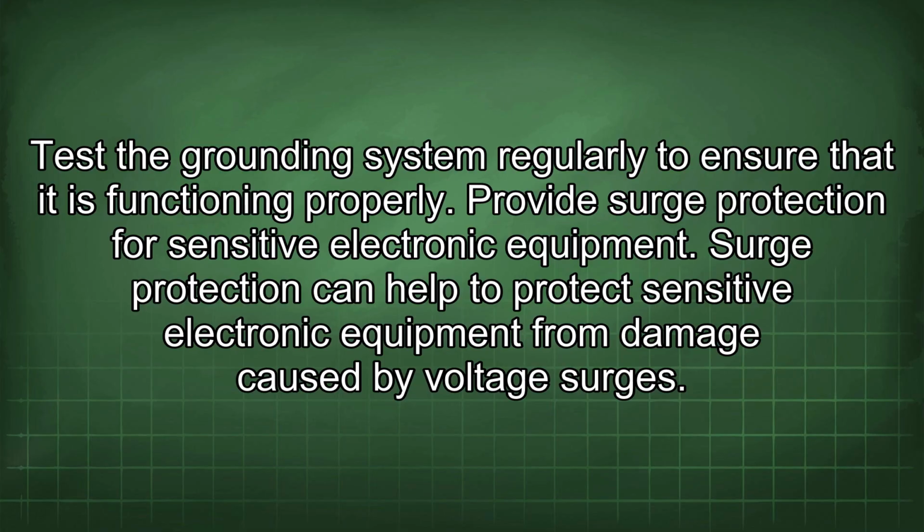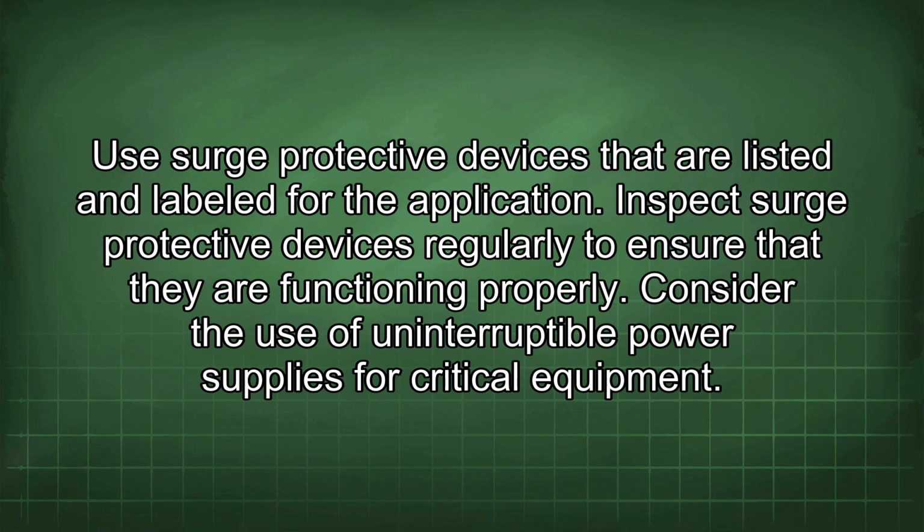Provide surge protection for sensitive electronic equipment. Surge protection can help to protect sensitive electronic equipment from damage caused by voltage surges. Use surge protective devices that are listed and labeled for the application. Inspect surge protective devices regularly to ensure that they are functioning properly.